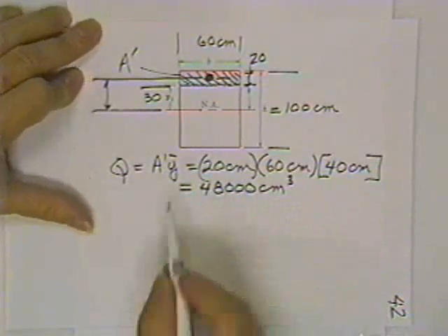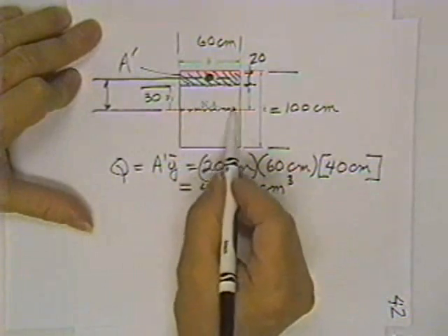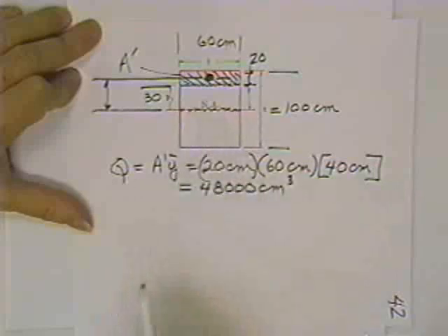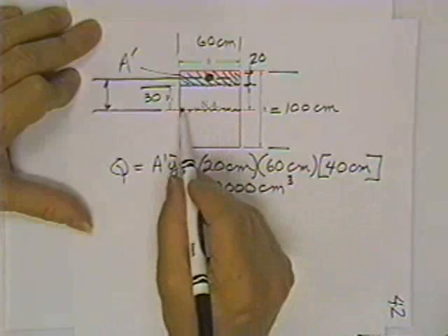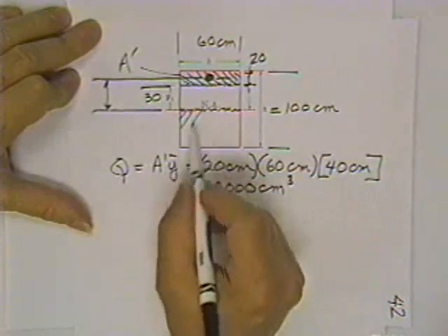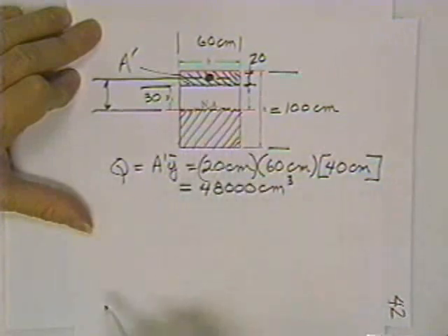Now I might go back to the boss and say, you know, you'll find some bigger shearing stresses right in here. He'll say, are you sure? I say, yeah. Big shearing stresses live on the neutral axis. He says, how big? I would go and put my finger on the neutral axis. I would crosshatch everything above that line.